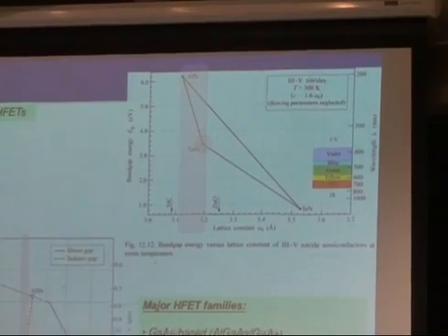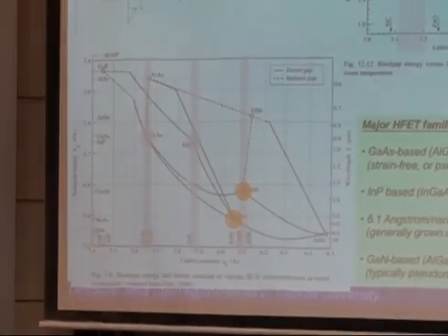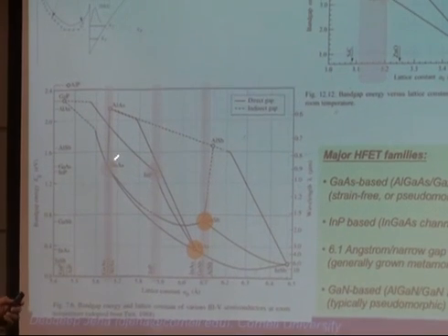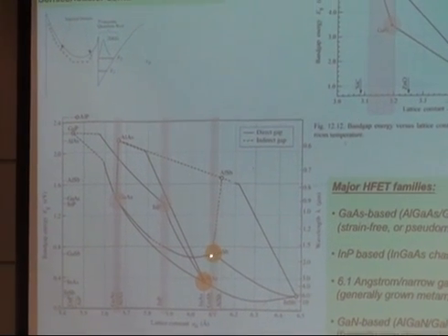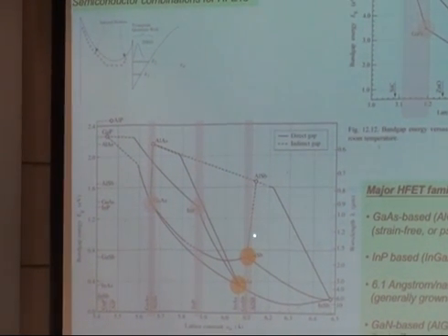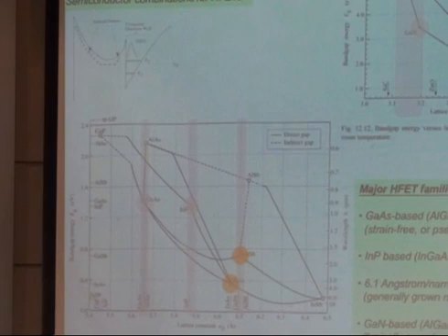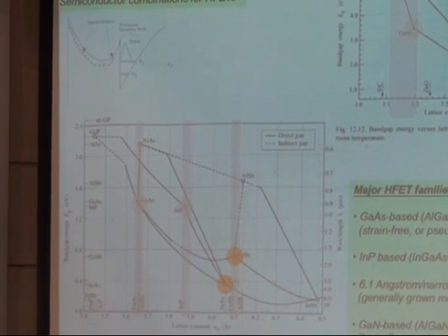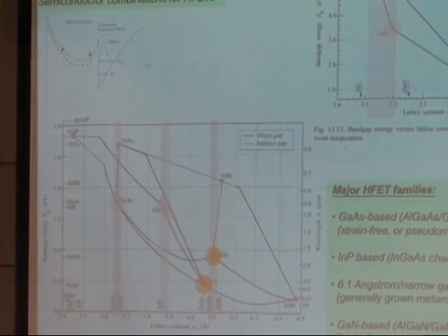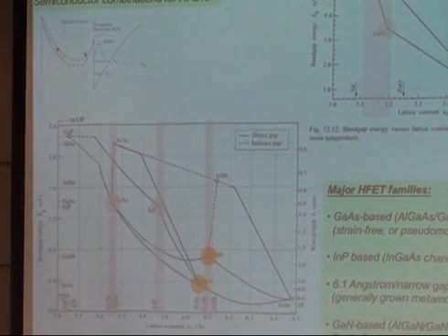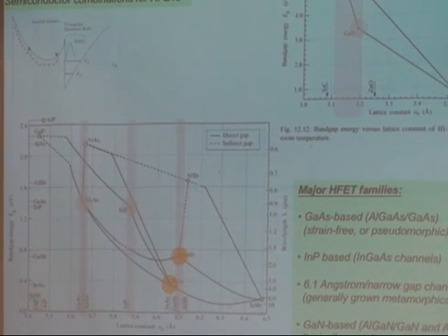The first thing that was done is you make the substrate semi-insulating first, and then grow large area substrates. That has already been done for gallium arsenide and indium phosphide. Gallium antimonide is kind of being done. Gallium nitride, large area substrates have been hard, but luckily people have been able to put it down on all kinds of other substrates like silicon carbide, but it's coming along as well.